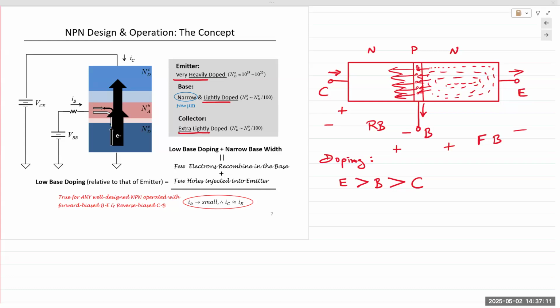It is not a symmetrical device. So in the lab, if you take your transistor and flip it, plugging in the collector where the emitter was, everything will be the same. Your transistor is not going to get blown out, but it's just not going to work. And I'll get to that point later also.